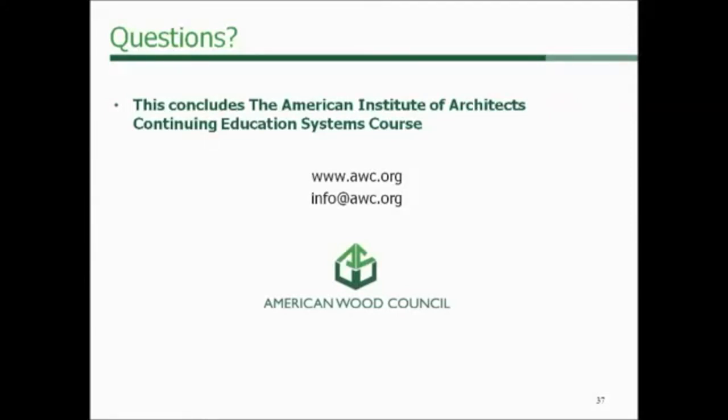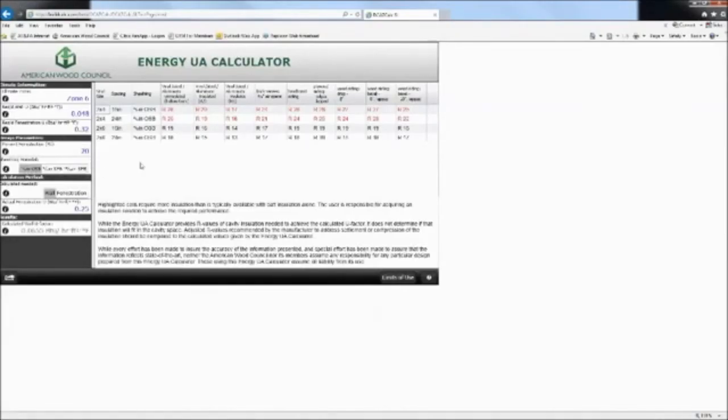Okay, great. Another question, does the Energy UA calculator have 7/16 OSB? Yeah, so the difference between a 7/16 OSB and 3/8 OSB is practically none as far as the R value is concerned. So the answer is basically no. It's got what it's got, the 3/8. But how much is it really going to make a difference on your wall is very, very minimal. So it almost doesn't matter.